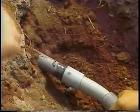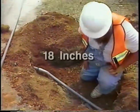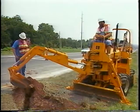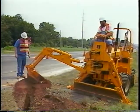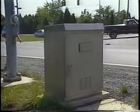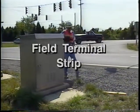Whether by itself or within a waterproof conduit, the cable should be placed in a trench at least 18 inches below the surface. Next, the trench should be backfilled with up to 6-inch layers. Then, use mechanical tampers to compact each layer to the density of the surrounding ground. The lead-in cable will end inside the controller cabinet at the field terminal strip.